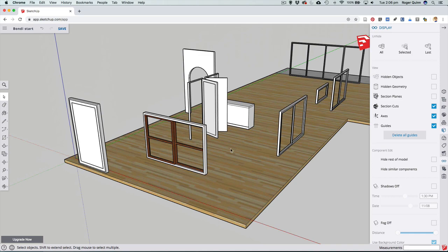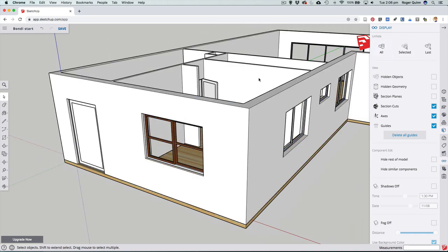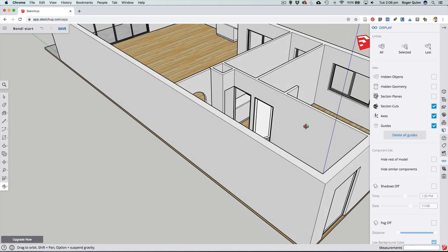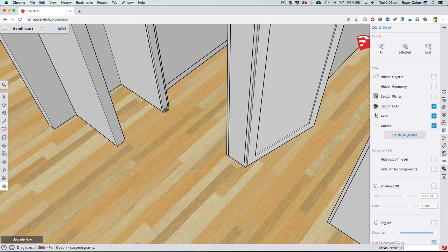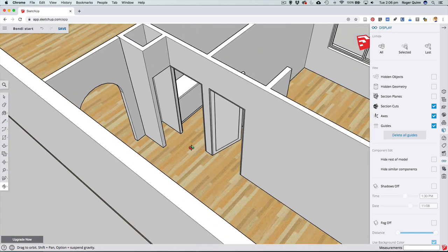With the internal doors, again I'll just bring my walls back. The only difference is that you sometimes don't really see that internal frame going across the bottom, and the reason is you don't want to interrupt your floors. You have carpet or tiles or floorboards, and you don't want to see a thumping big frame for your door going across the bottom. Some houses and architectural styles still do have a panel across the bottom, but most don't.